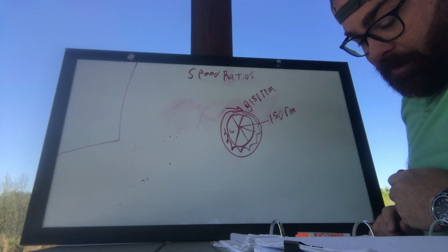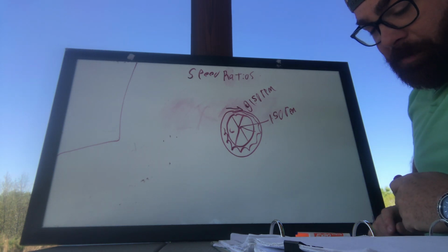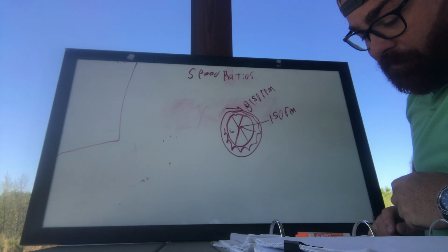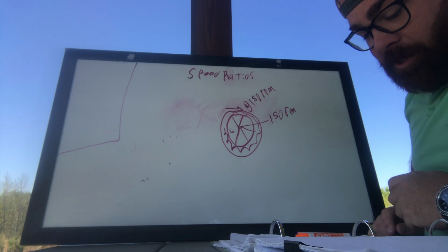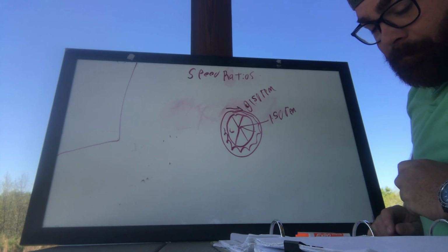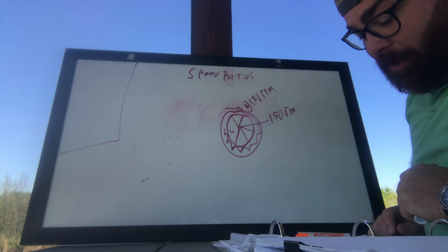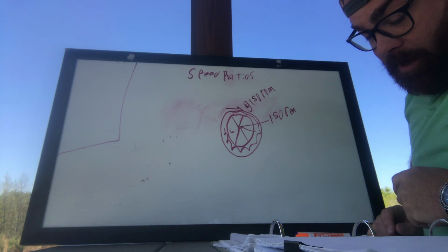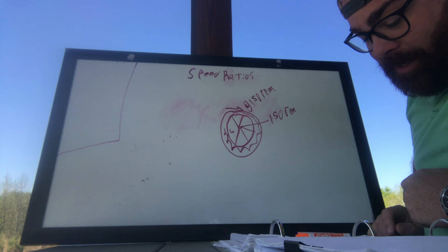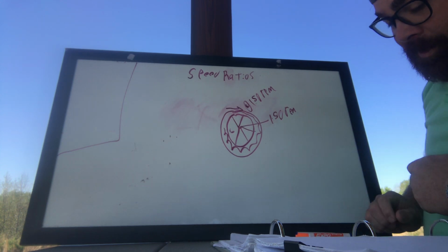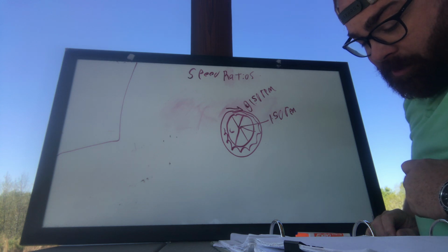Regardless of their diameters, the difference in speed and torque transmitted to the gears connected to the pedal is a function of the ratio of the connected gear diameters. To determine the proper pulley or gear diameter for an application, both the speed of the drive pulley or gear and the desired speed of the pulley or gear connected to it must be known.